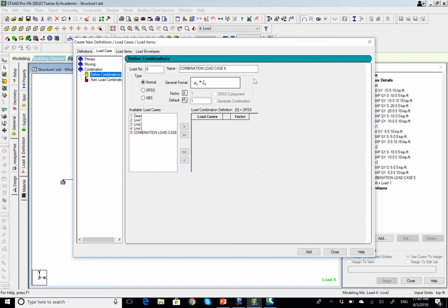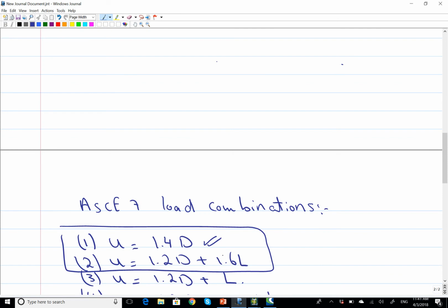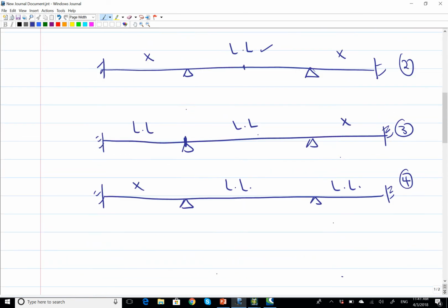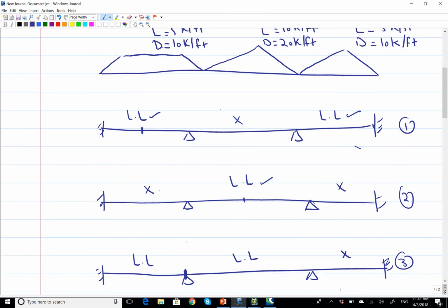We're going to input just 5 load cases here in a minute, okay? 113, it's going to take you, what? 30 minutes, maybe half an hour, okay? So it's not something scary, okay? So now, what we want to do now is 1.2 multiplied by the dead load plus 1.6 times the live load. What live load? I have to input 4 load cases. Here, I'm going to start with this. The live load here and the live load here, okay?